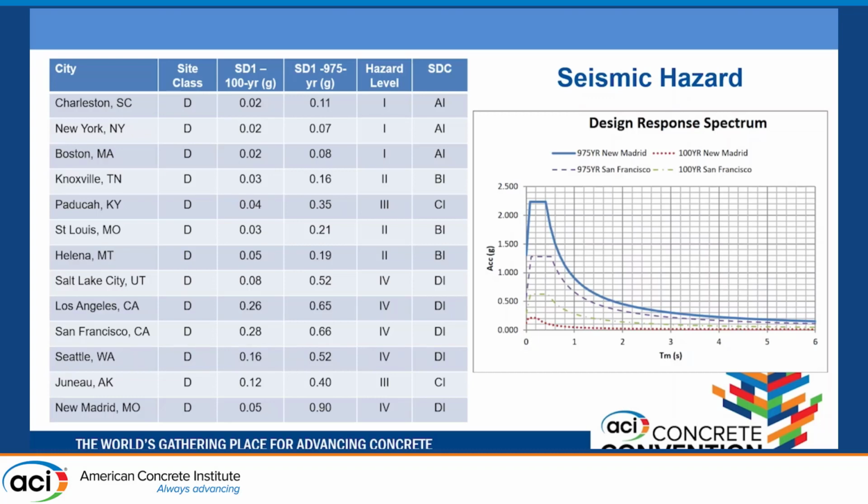1,000 years corresponds to, and when you talk about return periods versus design life of a structure, it's not quite illuminating what you're doing. It's better, really, to talk about it in terms of the probability of exceedance in a certain number of years. So the 1,000-year event has a 7% chance of exceedance in 75 years, 75 years being the AASHTO design life of a bridge. For other load cases, we're designing for a 75-year life. So it was judged that designing seismically for a 7% chance of exceedance would be a reasonable thing, and that corresponds to the 1,000-year event.